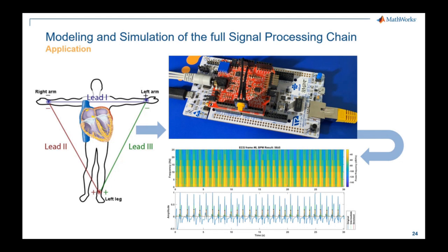And then once we have done our signal processing chain within the board, we will output the results. So here the results will be sent out via Ethernet using TCP/IP, UDP, and also a ThingSpeak communication channel. So we can send it onto a local intranet network, but also onto the internet to the cloud. That was the goal of this.